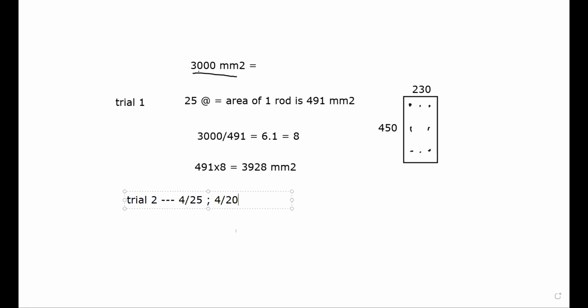So that has to be balanced. Sometimes, since the steel cost is more, we increase the column sizes, like footing sizes, and reduce the dia of the rods. That interpolation we can manage as structural engineers. That is a small thing we can do, but not completely avoiding the columns. That is a different story. We will come back to that later.